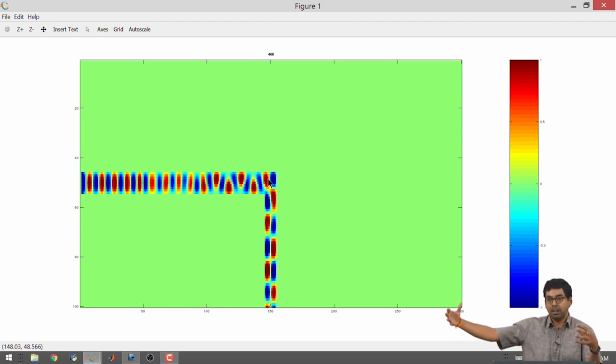But normally, if you keep a source and a detector on the same side, I mean in line of sight, it is hard to believe that you are getting the light directly from the source or through the waveguide. You will have trouble believing it. So, a better idea would be to bend the waveguide in some way, so that your source and the receiver are not in line of sight, and then actually prove that you are really having waveguiding action.